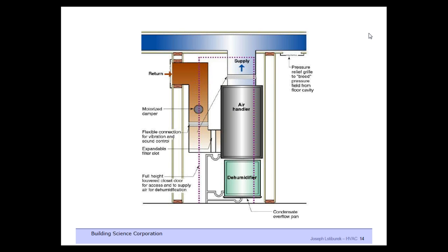It's possible to have such a system with a fully ducted return as opposed to a return closet. You're just basically going to be extracting air from the closet through your return system. So the approach can be made to work without an awful lot of cost. Next.